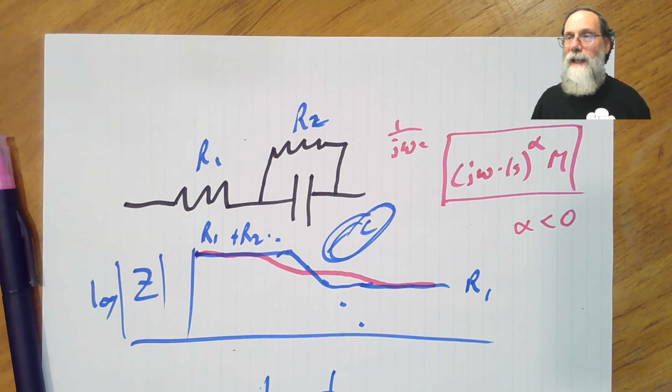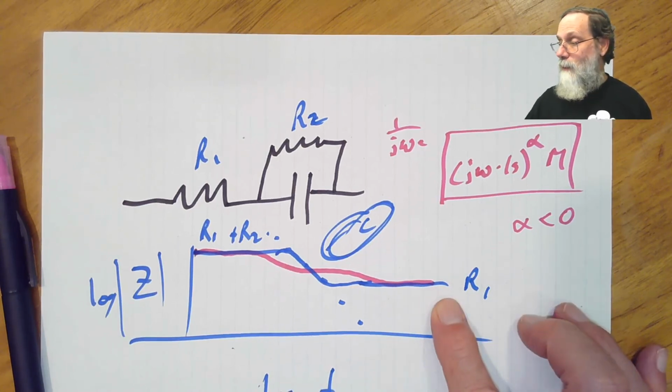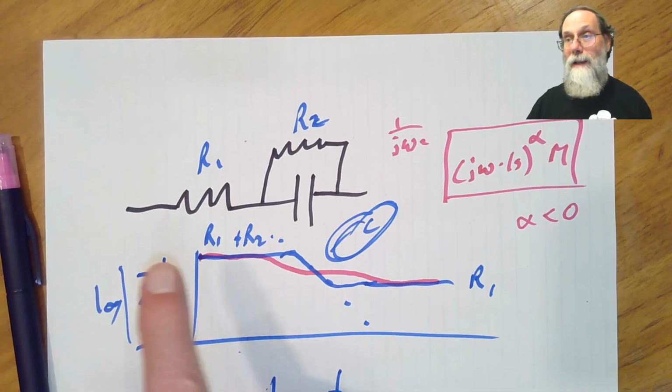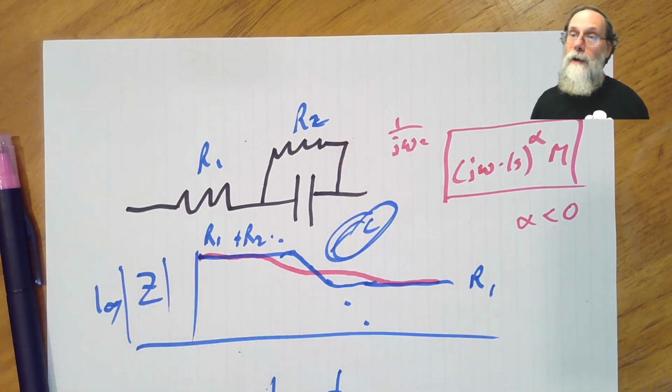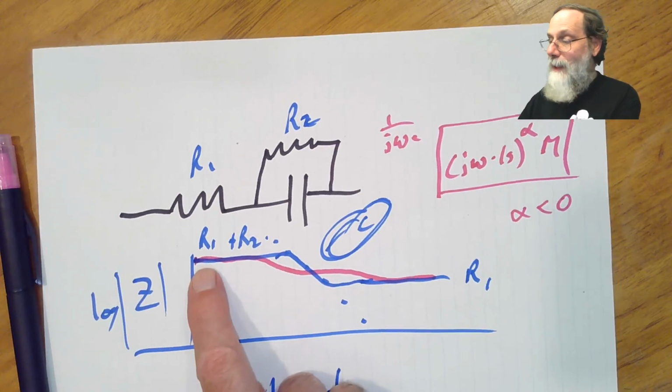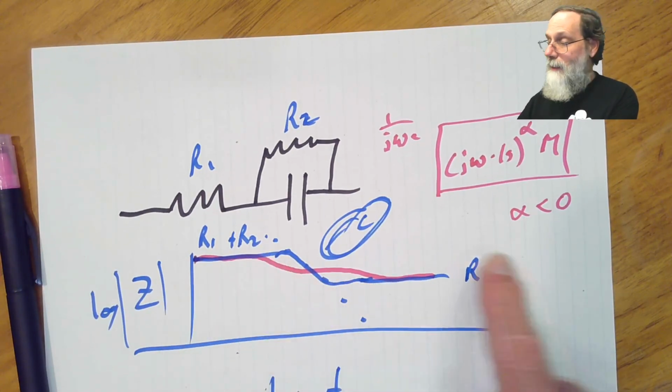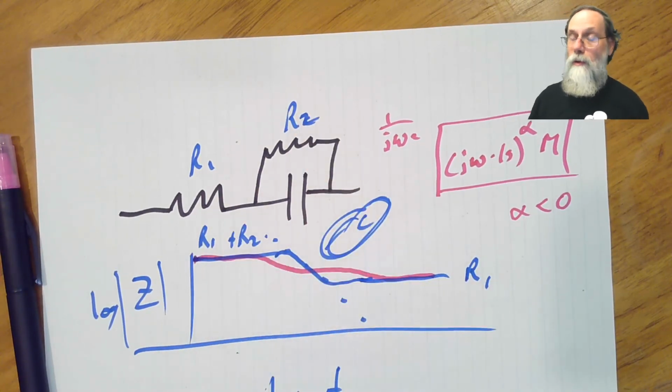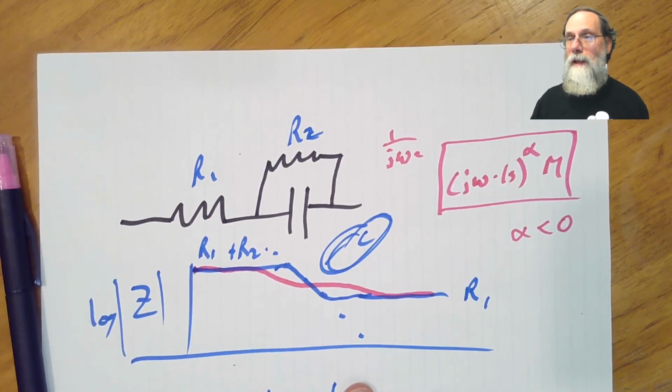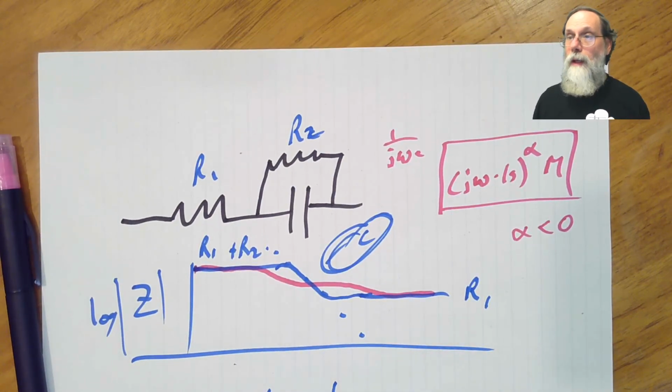If it slopes like that and then goes flat, then you might want to put a resistor in series. If it starts out flat and then slopes down, you might want to put a resistor in parallel. So if you've got the entire behavior with a flat spot, a slope, and a flat spot, then two resistors and a capacitor or capacitor-like nonlinear impedance. So there are a lot of different models all encapsulated in that one schematic, because you should leave out those components whose values can't be estimated. And that's basically it for what you need to do with electrodes.